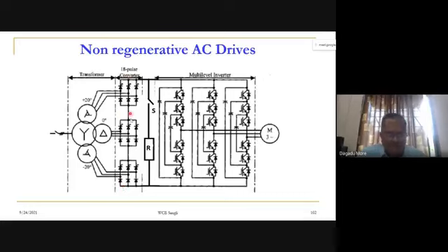Here, why are we going for a series configuration? We require a higher DC link voltage. For a drive above 3.3 kV, we definitely require maybe 5 to 6 kV DC. So with this high voltage DC, we can obtain it with the help of this.